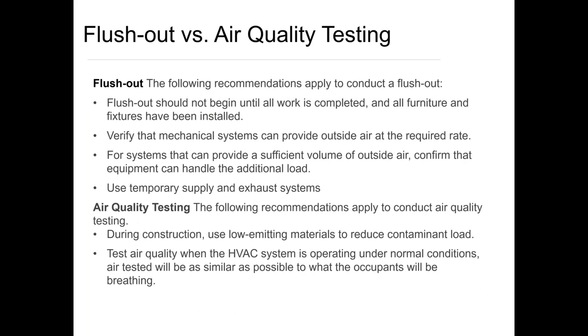So here we're looking at the option to either pursue flush out or air quality testing. I would say there are pros and cons to each one, so it's really up to the building team to choose which is the best path. So the flush out is following certain recommendations to do a full building flush out, which is done when the building is completed, when all furniture is installed. So essentially construction is done, furniture moves in, and then the flush out is started.